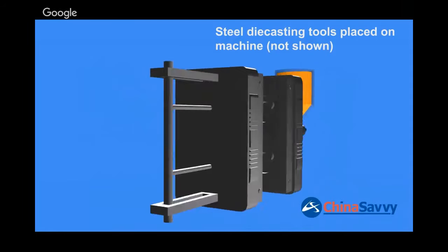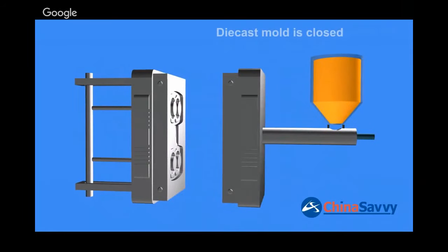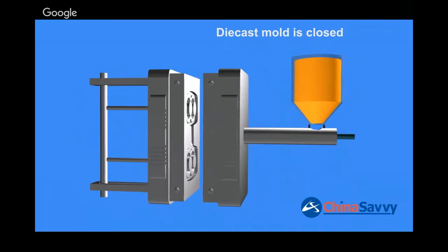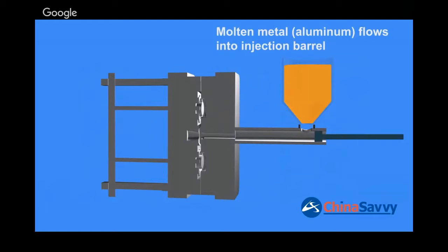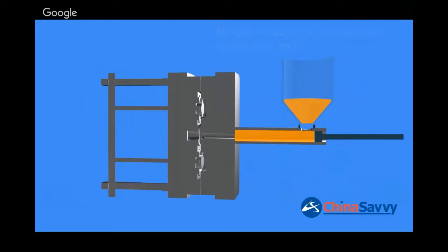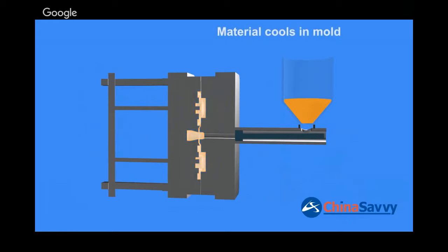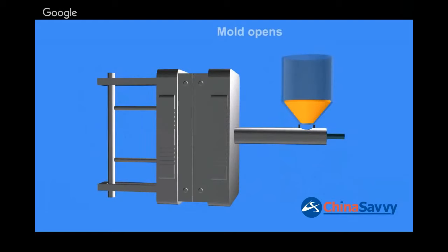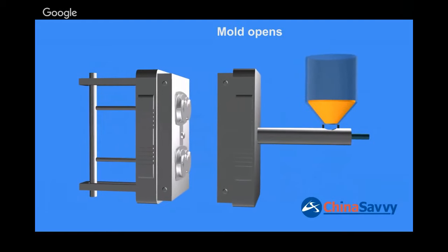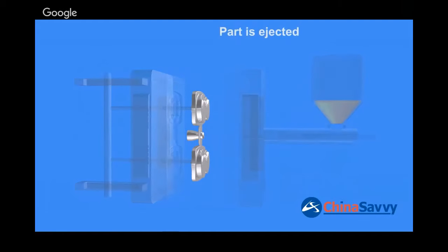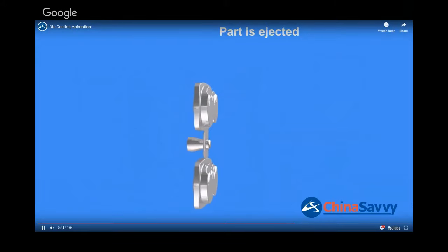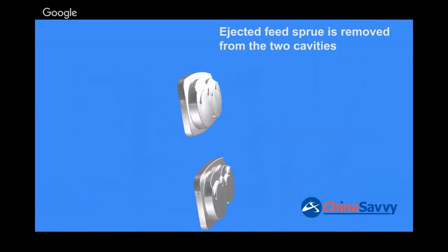You can see the molds inside, and over here on the right hand side is the molten metal. It's pushed in again under very, very high pressure. You've got these nozzles, and that injects it into the mold. You can see there are the sprues and the gates, the types of words that we've used when we talked about the other casting as well. You'll find those same features here. That's essentially the process.